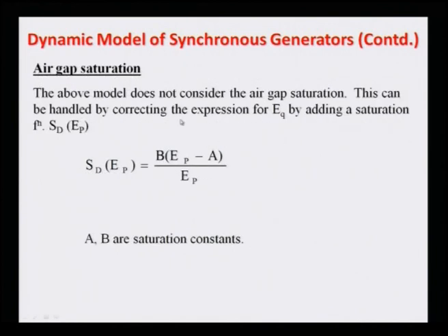Now, we can also include some double primes, like E_d'' and E_q'' equations, then we are going for the sixth order model as well. So again, it depends upon the need, you can go for more detailed modeling of the synchronous machine, but normally, as I said in the very beginning, for the practical analysis the third or fourth order models of the synchronous machine are used.